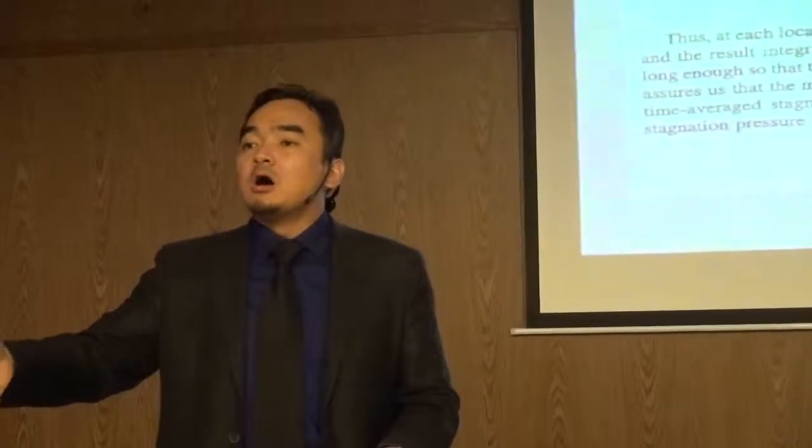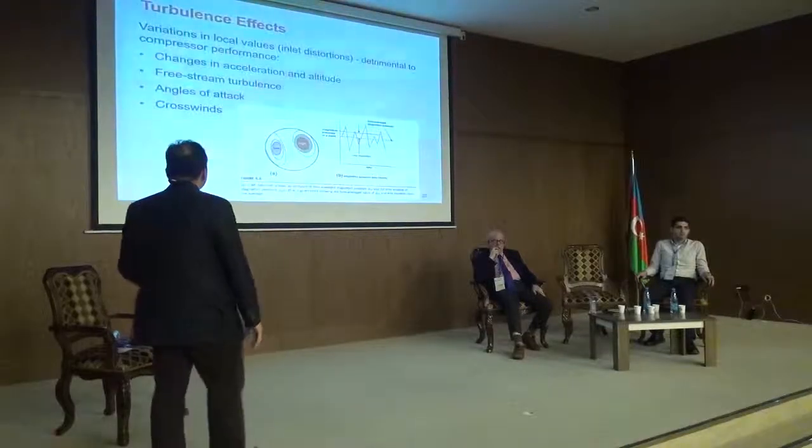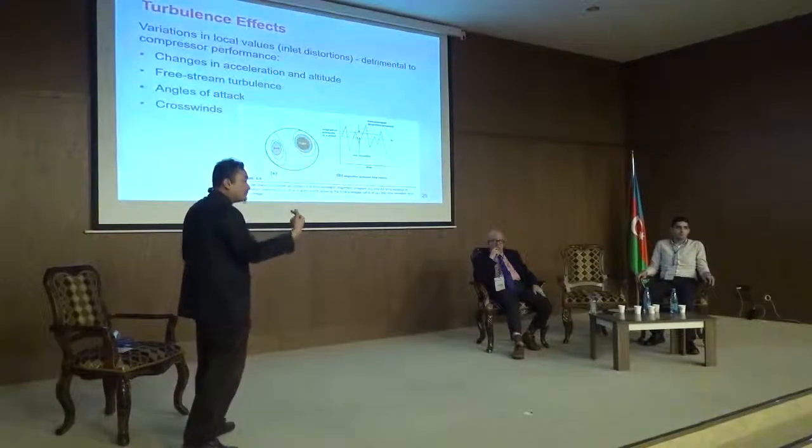So basically the pressure performance depends on the properties, the turbulence properties. At the moment you have shock waves, the properties of the pressure vary: the stagnation properties, the mean properties, and also the turbulence properties. So this will affect the performance of the compressors and the inlet.